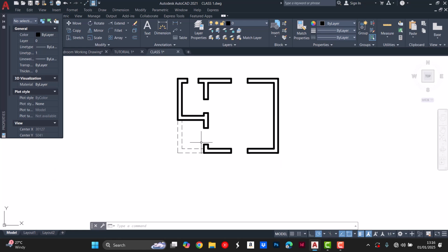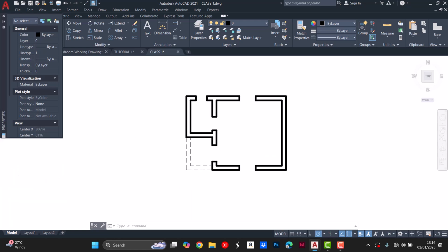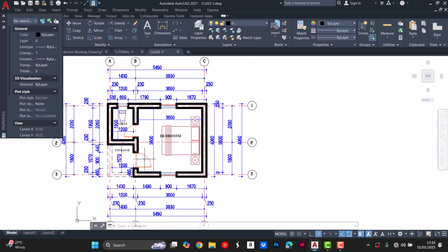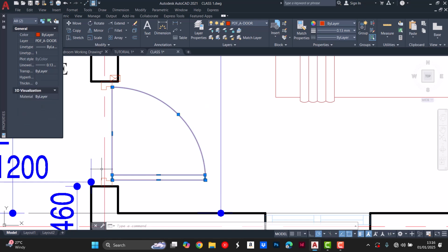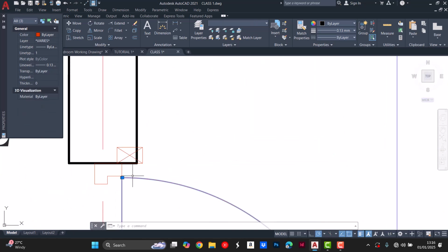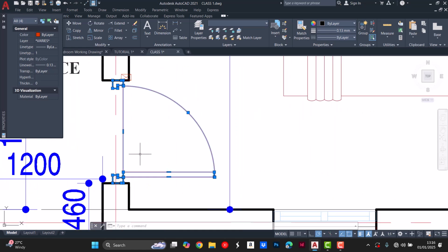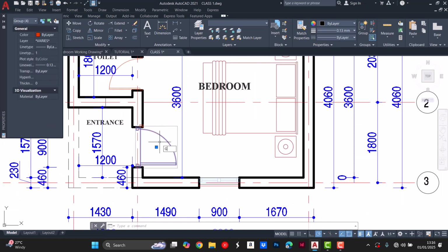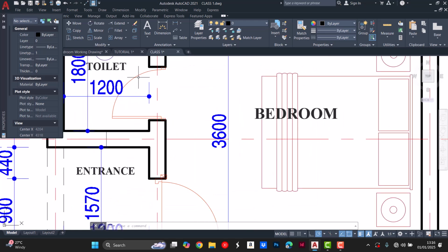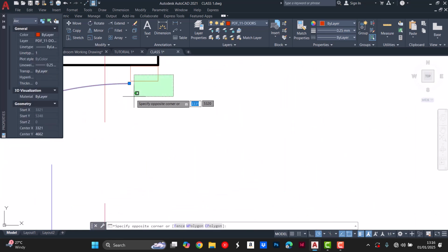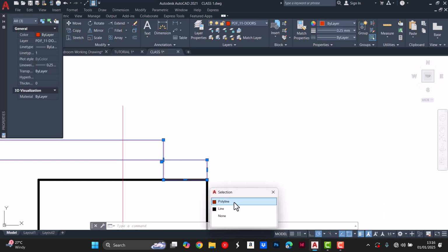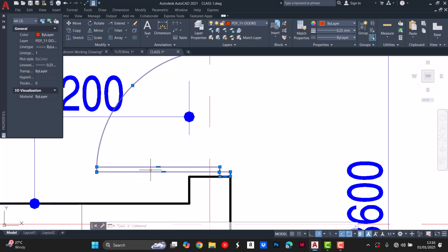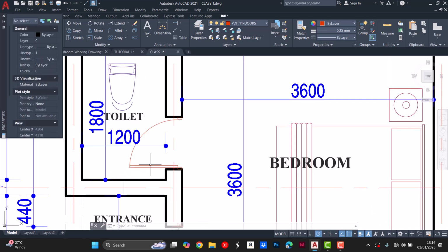Okay, so we have our opening there. So you have your component, you can copy it. I have mine here. You can download it if you have. Okay, this is supposed to be a block, but it seems like it's broken. So I'm going to group it. I just click on it and I type the group command. It just groups it together and makes it a block. That's what I wanted. I wanted the block, not a broken piece. I think it's because I copied it from the other tab to this place. That's why it's that way.